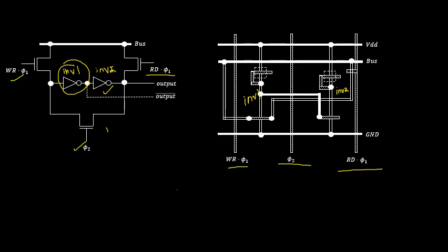So I am concentrating here in terms of NMOS design style, which means that these two inverters will be NMOS inverters. So a single NMOS inverter I will draw over here. It will be having in the pull up part the depletion type of NMOSFET whose gate terminal is shorted with the source terminal of the depletion type of NMOSFET.